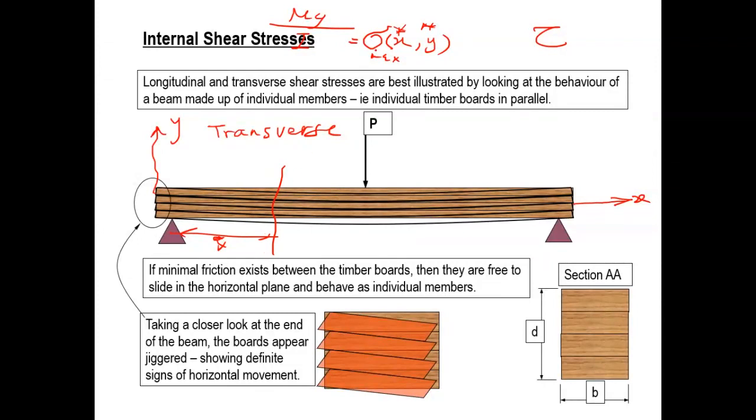And then remember, for normal stress, it is always maximum either at the top or at the bottom, depending on which one is farther from the neutral plane. Why is that? Because y is the distance of the point from the neutral plane, and the farthest point is either the top or bottom one. So we don't have any problem with that. Hopefully everyone, at least from a concept point of view, knows what we are doing.